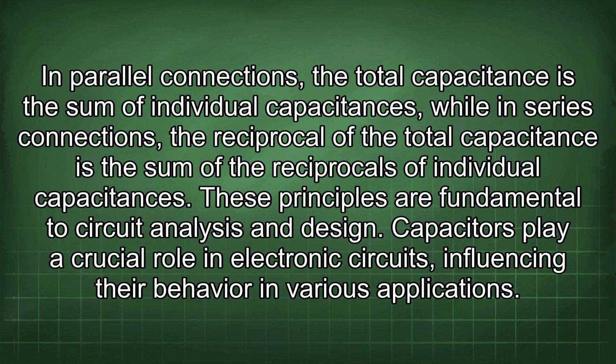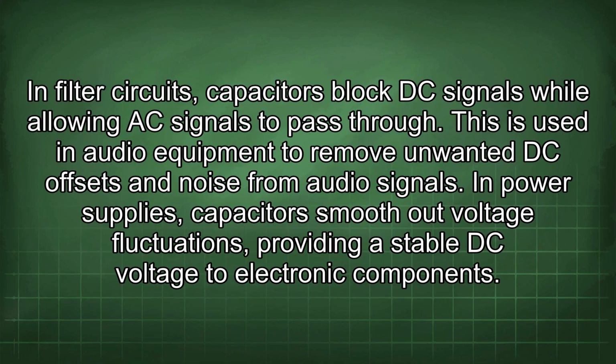Capacitors play a crucial role in electronic circuits, influencing their behavior in various applications. In filter circuits, capacitors block DC signals while allowing AC signals to pass through. This is used in audio equipment to remove unwanted DC offsets and noise from audio signals. In power supplies, capacitors smooth out voltage fluctuations, providing a stable DC voltage to electronic components.